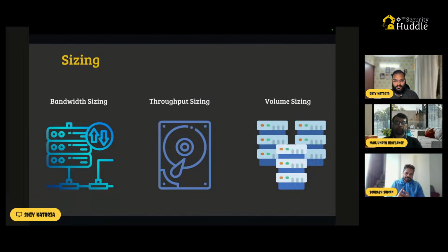Let's suppose you have 100 systems. Each system is generating 1 KB of log per second. How much traffic will it occupy? Do we need a separate cable to be laid, or do we need to create a separate VLAN on the existing copper cable or fiber optic cable? Or if the log size is very small, can we just accommodate it on the same process control network without any interference? That type of study we need to do.